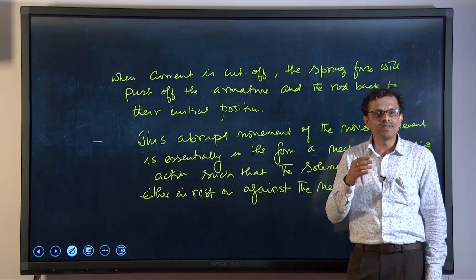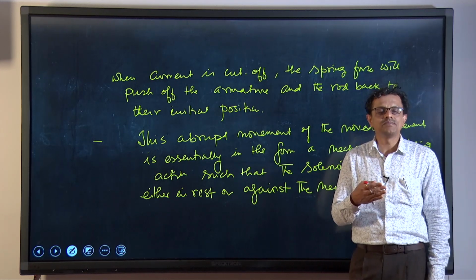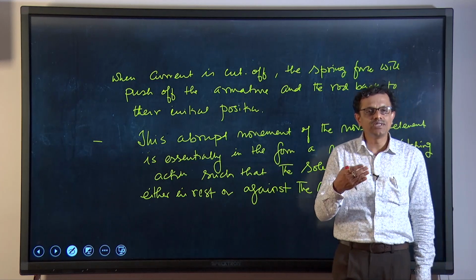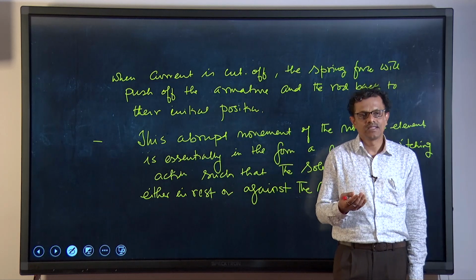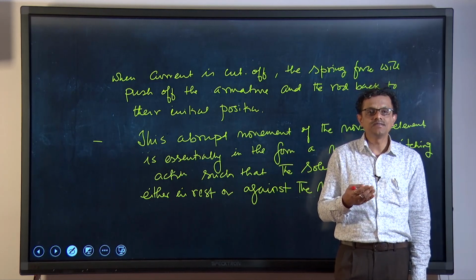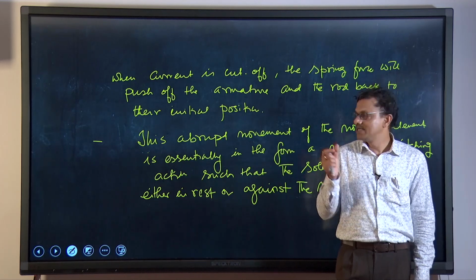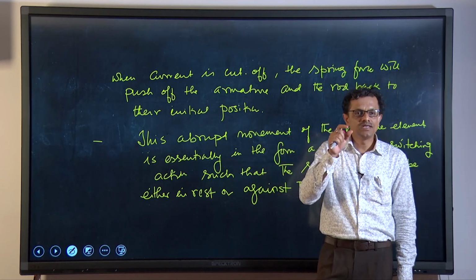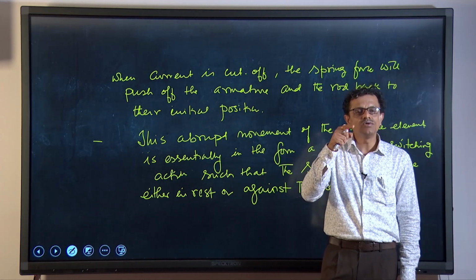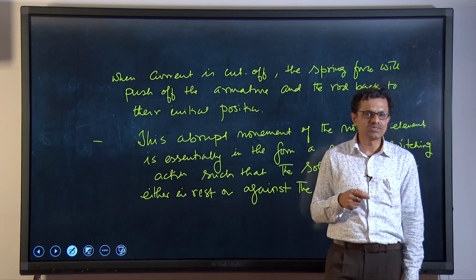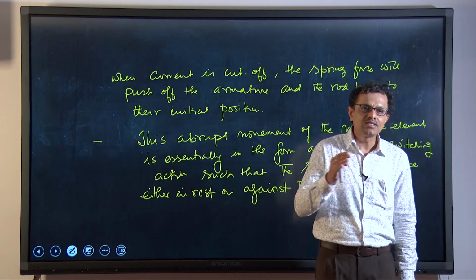If that mechanism is connected to the valve of the fuel injector, or to the valve of exhaust gas recirculation, then by switching the solenoid, either allowing the current to flow through the coil around the steel frame or not, we can control the movement of the armature and of the mechanism connected to the rod.